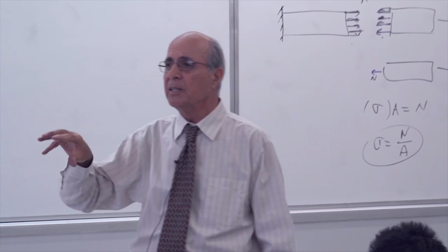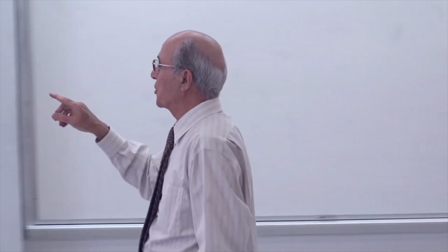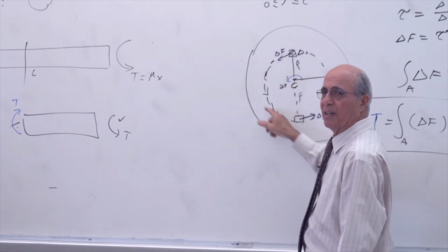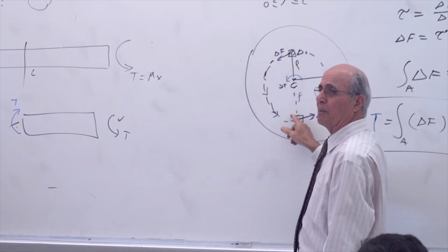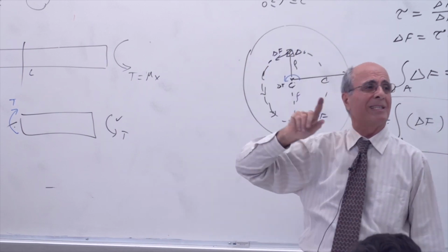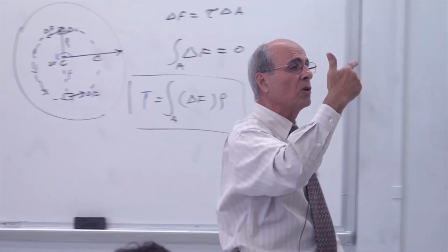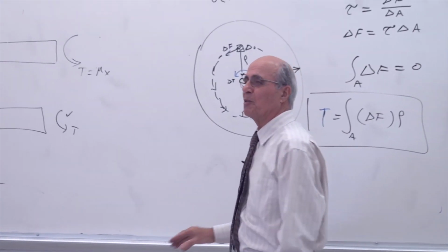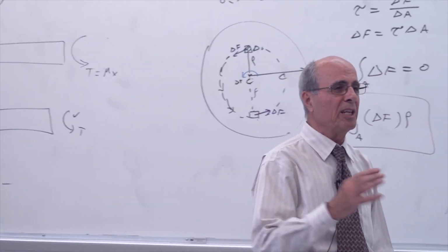Put everything in boxes and remember that. The stress at the center, one more time, is 0. Stress is in circular format, and as we're going up, the stress is linearly changing, and the maximum is on the outside. Very good. Now let's get to the next 4 or 5 minutes, which really puts you in.